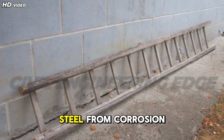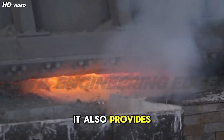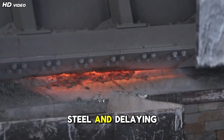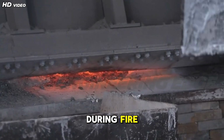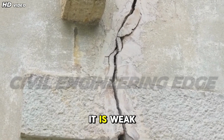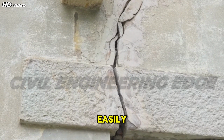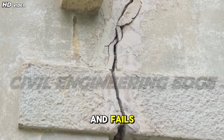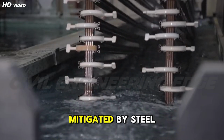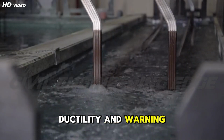Concrete cover shields steel from corrosion caused by moisture and aggressive chemicals. It also provides excellent fire resistance by insulating the steel and delaying strength loss during fire exposure. However, concrete has limitations. It is weak in tension and brittle in nature, meaning it cracks easily under tensile stress and fails suddenly if overloaded in compression. This brittleness is mitigated by steel reinforcement, which provides ductility and warning before failure.